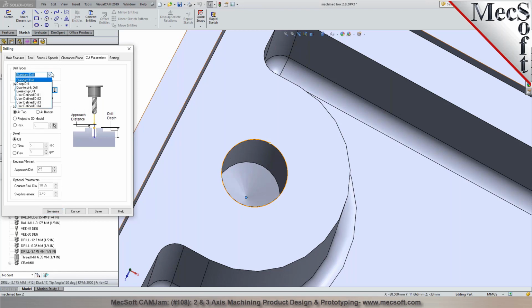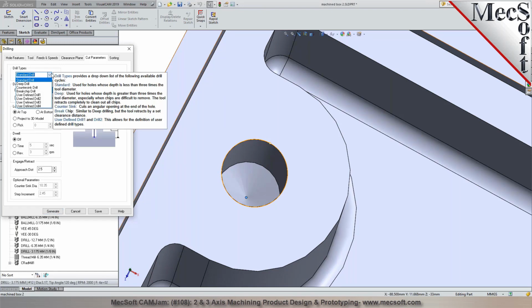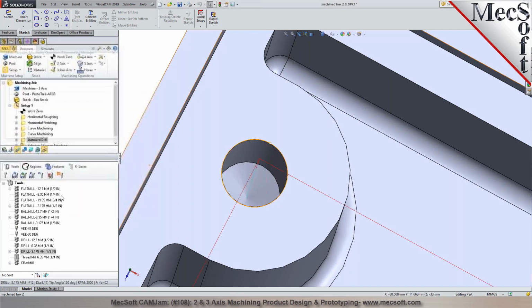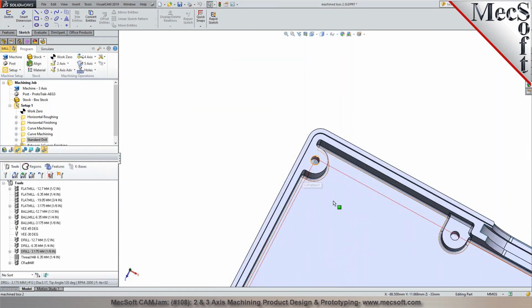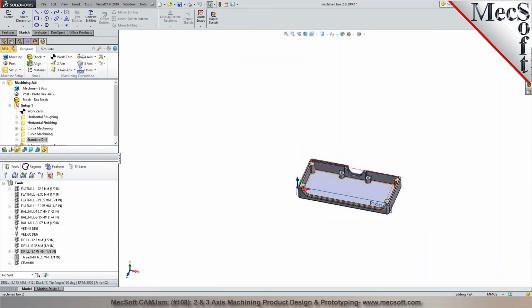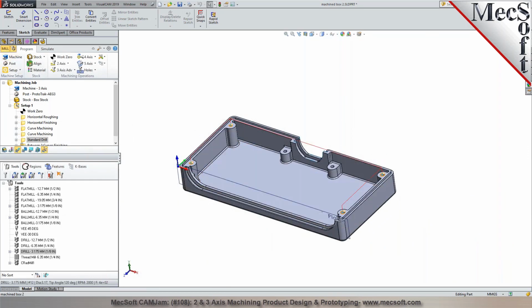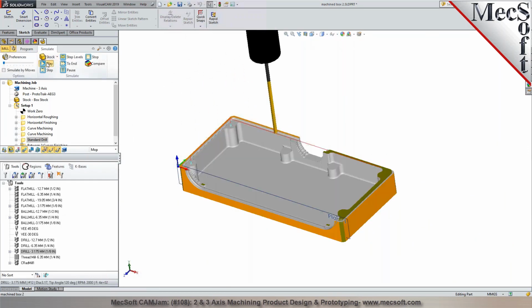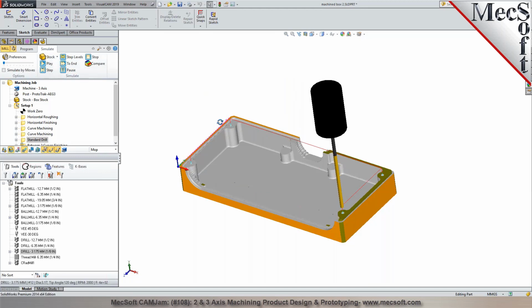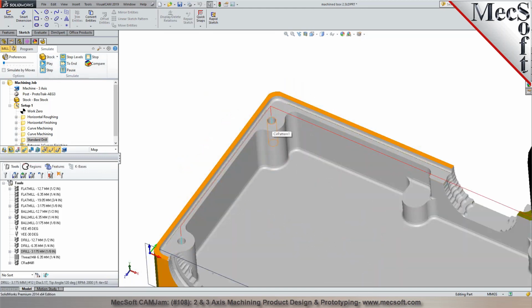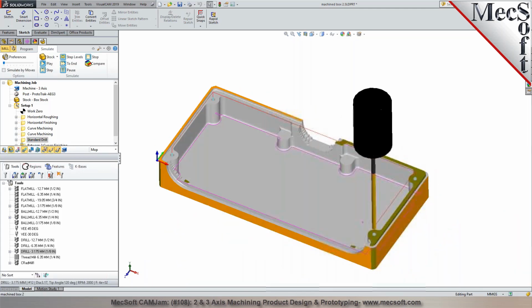generate. You can do standard drill, deep drill, countersunk, break chip, so we have all the drill cycles built into it. And if the controller for some reason wants to output a linear motion, we can output as a linear motion as well. Okay. What was the project to 3D? Yeah, so it'll automatically project if the point that you select is out in space. In some cases, you may want to drill at random holes in different heights. So the drill point gets projected down to the 3D model. Depth can be determined by projecting down to the 3D model.